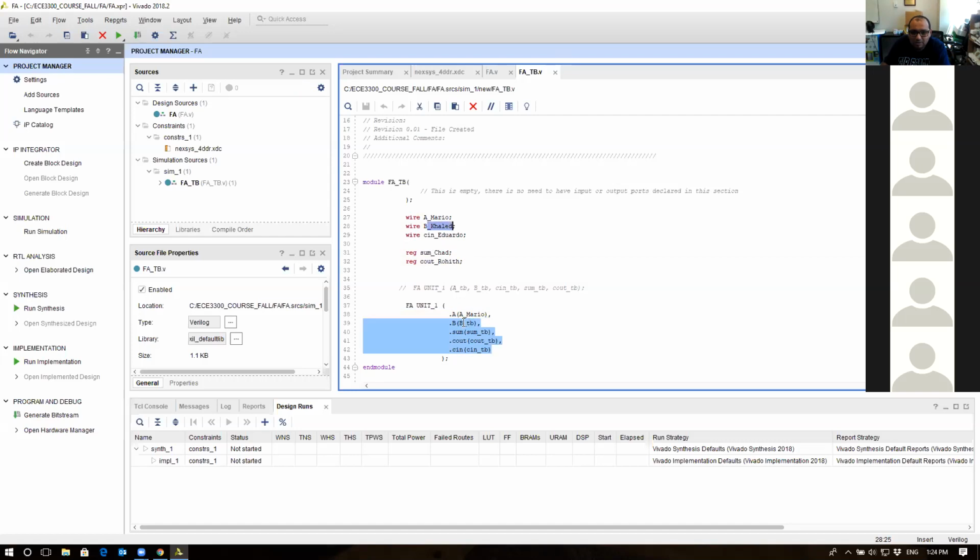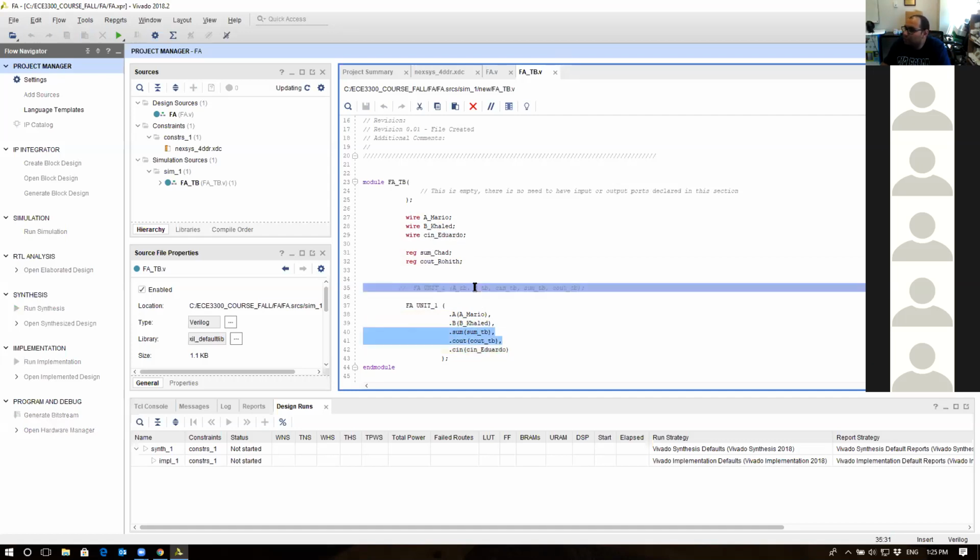Professor, yes, sir. If you wanted to, you could actually flip the wire reg declaration in the test bench if you flip it on the full adder module. That would work as well. Here it will be wrong. If you flip, it will be wrong. But here, the order is not important. You understand my point? So that's why the second approach I like more. It's more systematic.